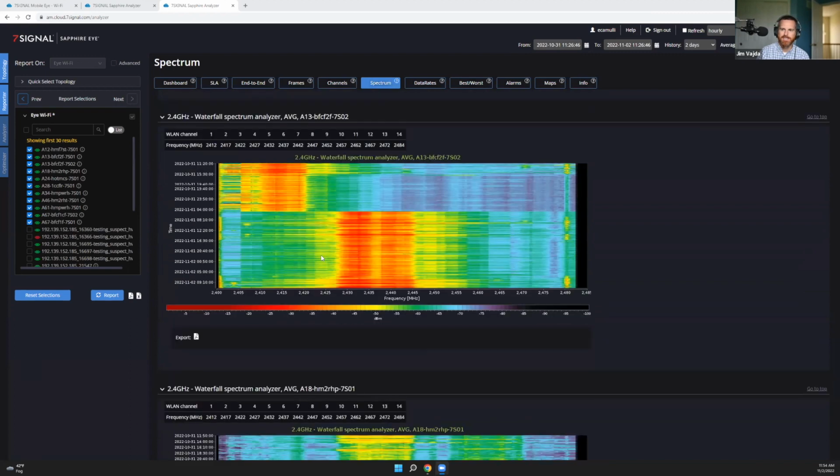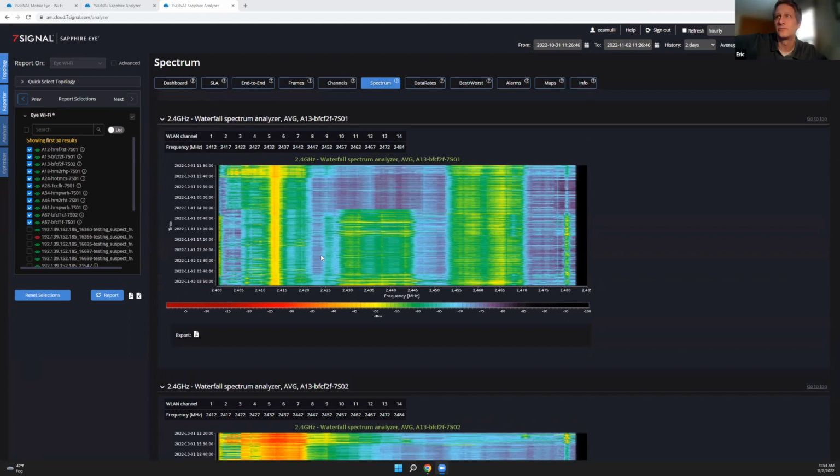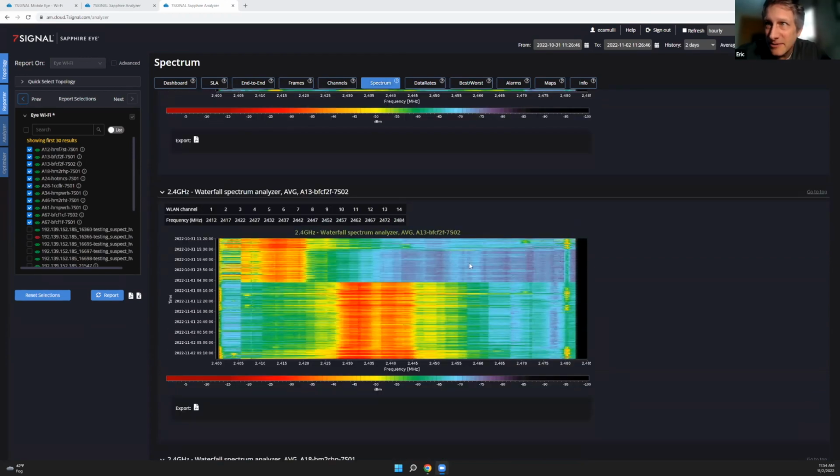Definitely got some high usage going on with all that red. Exactly. And it's transmitting 24/7. The timing of transmission is interesting too. Yeah, that's true, because normally we would see something more like this where it was intermittent, and obviously here's your advertising channel on the right. You've got another advertising channel about right here, and then you have the other one on the far left right there. When you see this action going on, especially with the BLE advertising channel lit up the way it is, it indicates Bluetooth in use, and you can see it moving back and forth.